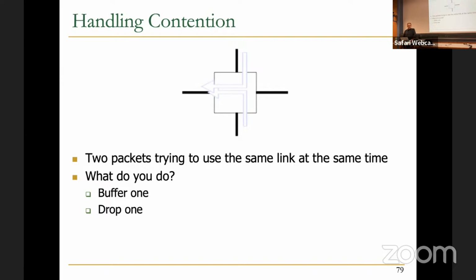But normally in network on chip, or interconnection networks, we don't drop packets, we usually buffer. Or we can misroute one using deflection, as we already discussed, these hot potato things. Of course, is there a trade-off between them? The answer is yes. Buffering is good, but it's expensive.